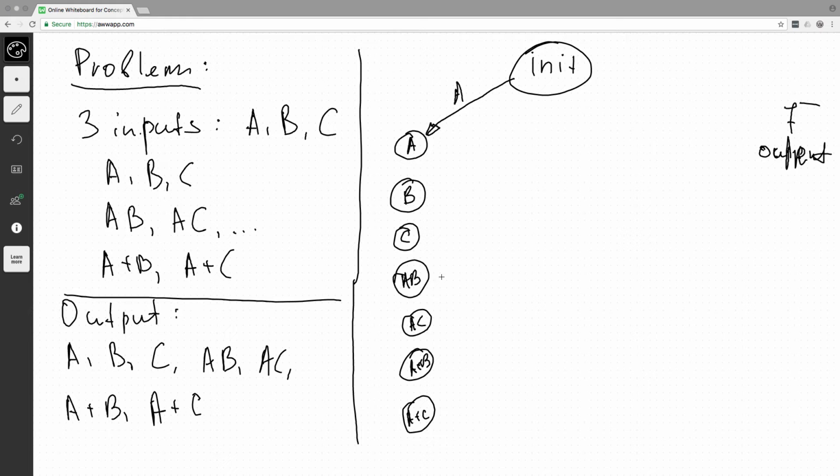And the memorization is actually the purpose of the finite state machine. So, in other words, sequence AB cannot be detected on the input side. Sequence AB can only be detected within the finite state machine. And that sequence will result in the transition to a state.